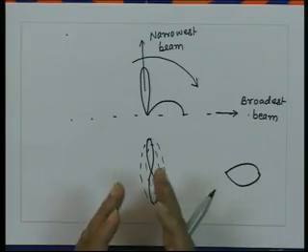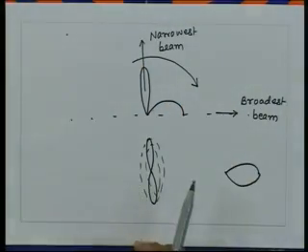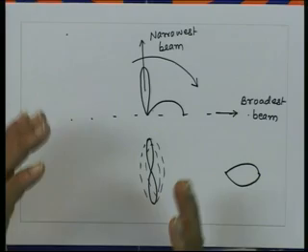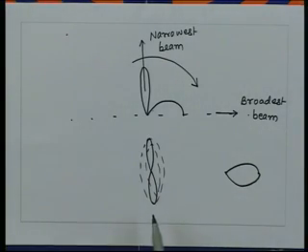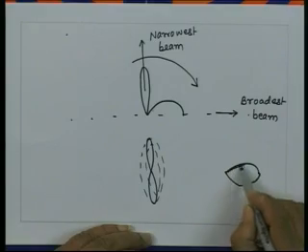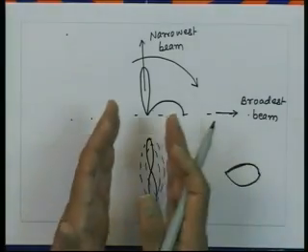So, in one case, though the beam in the planar view looks like only a change in shape or a change in the half power beam width, if I visualize the radiation pattern in 3 dimensions, the radiation patterns are quite different in the 2 situations. The end fire will look more like a balloon like that, whereas the broadside would look more like a flat disk, which is a figure of revolution in this direction.